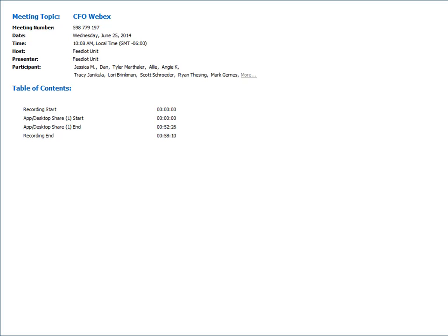Yeah, and coupled with that, oh, sorry, go ahead, Ben. I was just going to say, if you do find anything, make sure you have a camera with you. Email that engineer what you saw. I have conversations with them often: looks good, doesn't look like anything major, but the northwest corner looked like there was some potential going on, take a look, or there was an oddity running north-south on the floor. It doesn't look like a crack, but there's a different coloration. Just have that conversation with that engineer.